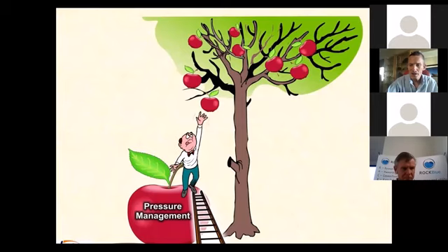The paybacks on pressure management can vary, typically from the 400 or 500 installations that we've designed and built. Typically anything from a month to 2 years would be your payback from a pressure management installation. And generally we are in the 3 months to 6 months range. But it can be as low as a month, it can be as high as 2 years.